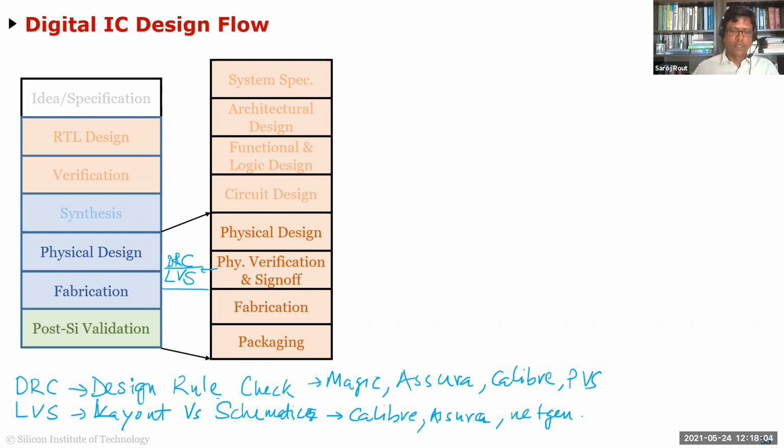For example, your seniors who are now in jobs with Savia are in the PDK team, so they are going to write these rule files. If you draw a poly gate over a diffusion polygon, that represents a transistor, and the extraction tool, like Netgen, will extract these polygons into devices.